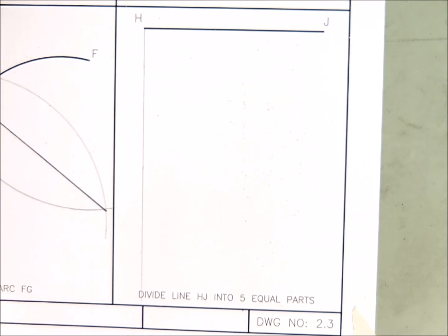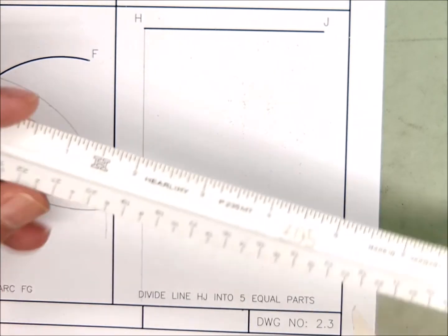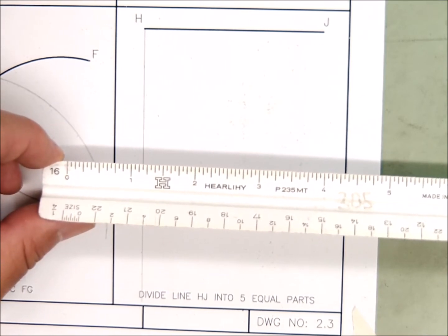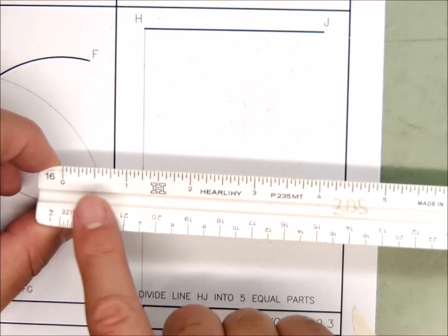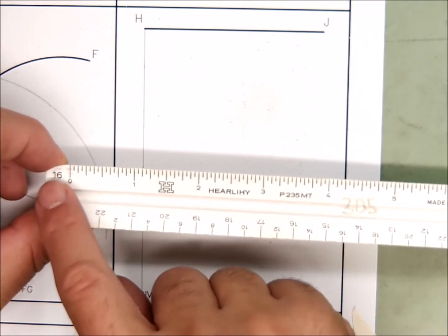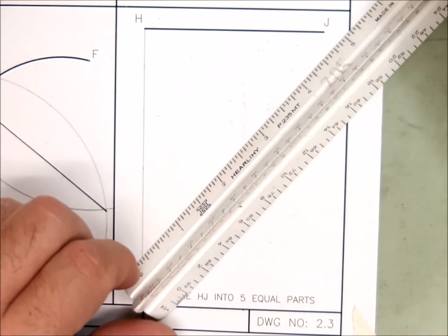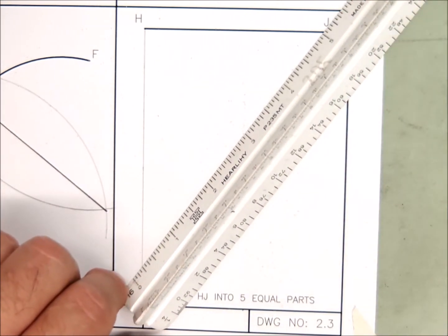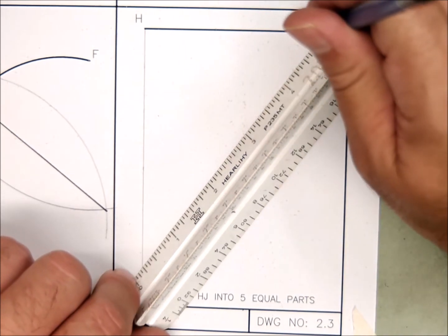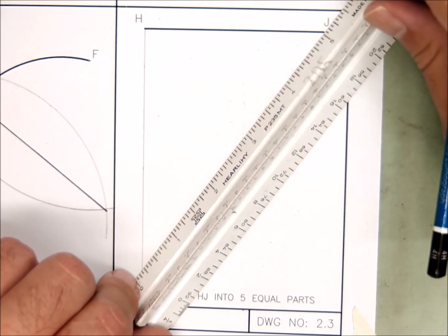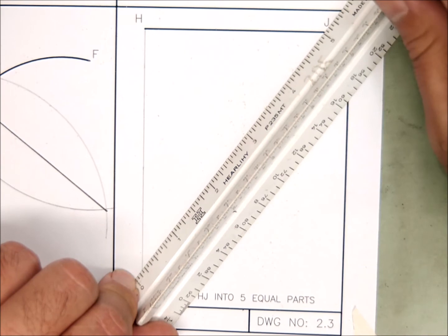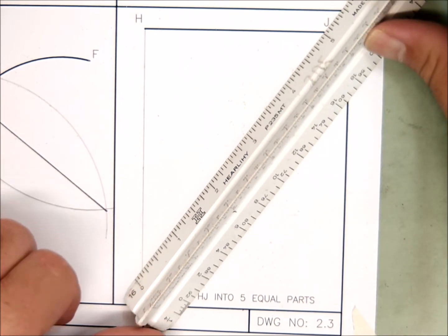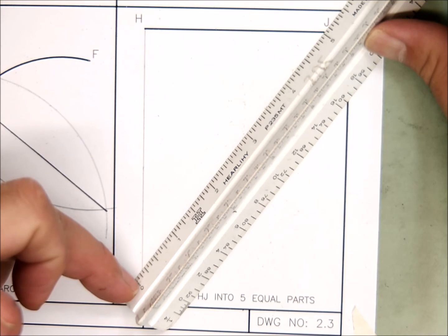Here's step 2. The problem is to create 5 equal spaces. So we are going to use our scale, we're just not going to use it in the way you think maybe. Okay, so we want 5 equal spaces. So find the number 5 whole inches on the regular ruler of the 16th of an inch breakdown. And I'd like you to take the number 5 and put it right at the end of point J. See, here's the line for 5 inches, and I put it right at the end of line HJ. And then what I want you to see is, you see where the 0 is down here?